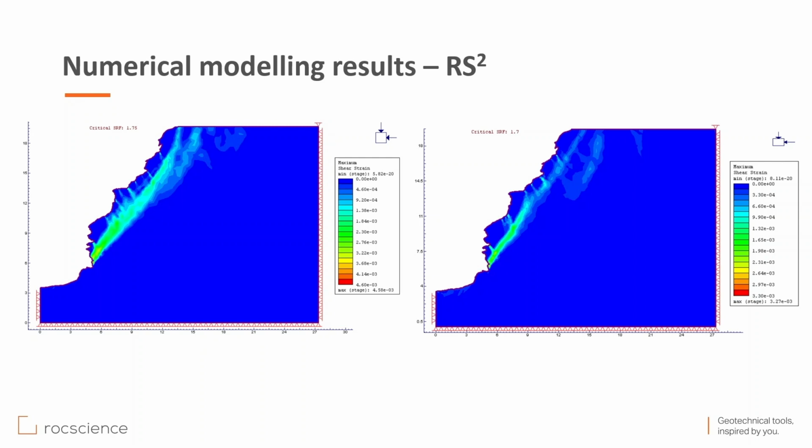Eurocode 7 represents a major change in design philosophy. With Eurocode 7, partial factors of safety are applied to different components of the analysis. The partial factors are applied prior to the analysis of given design values. The final result is an over-design factor which must be greater than 1 to ensure the serviceability limit state requirement is satisfied in this case.